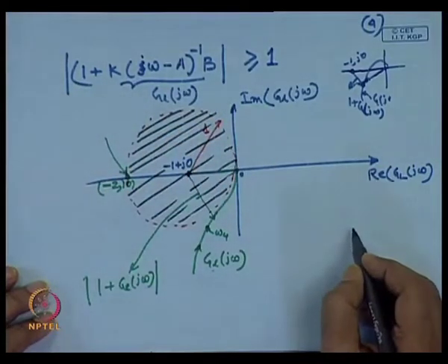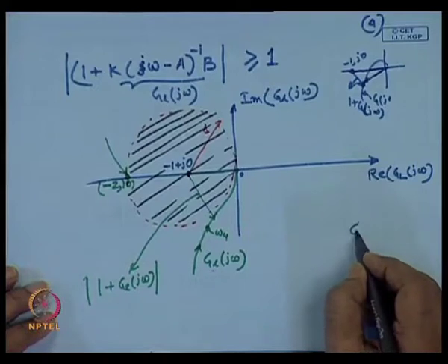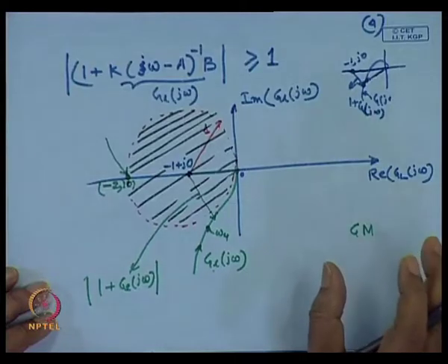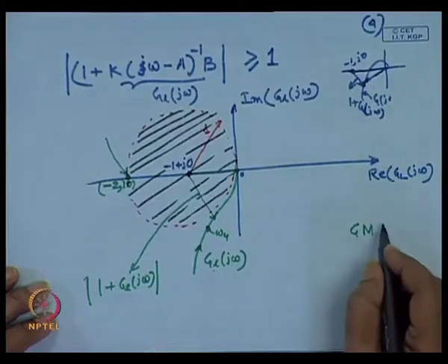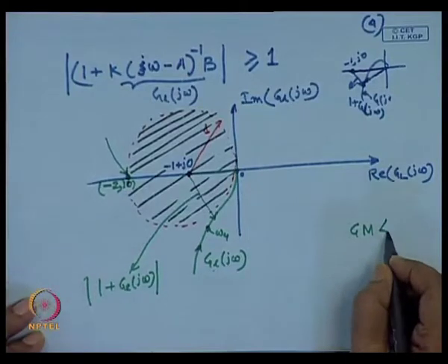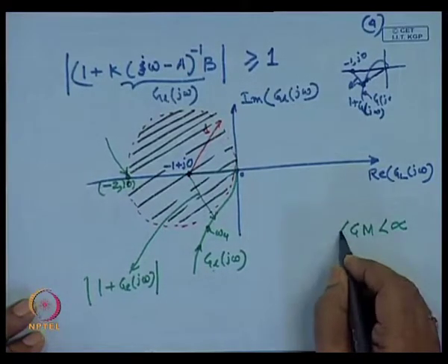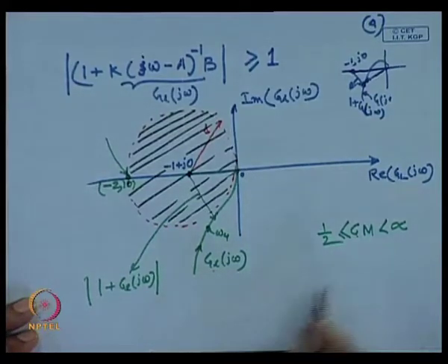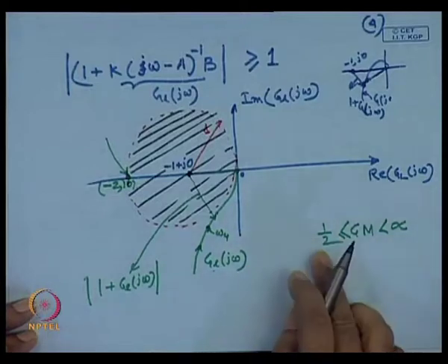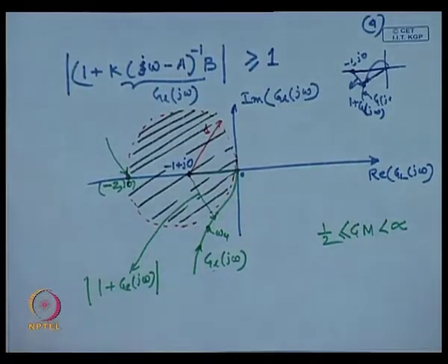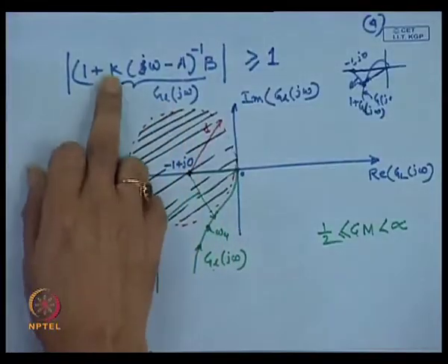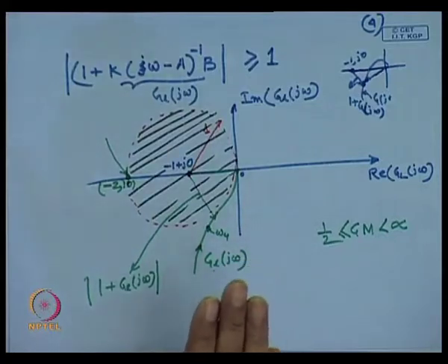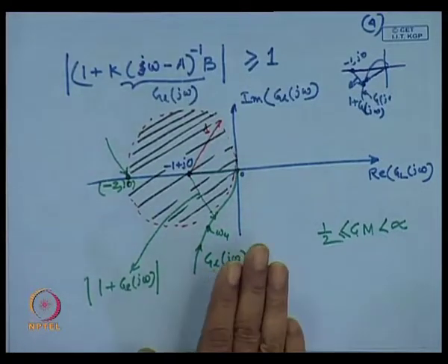So, we can say that for the gain margin of the LQR designed controller based control system, we can increase the gain up to infinity and decrease the gain at least to half. Okay. So, our gain margin is from infinity to half. Let us call the present gain we got for this system 5. You can increase the gain 5 up to infinity.